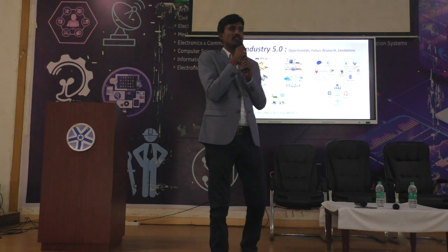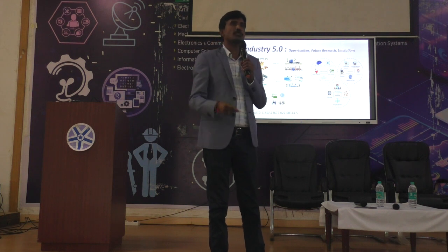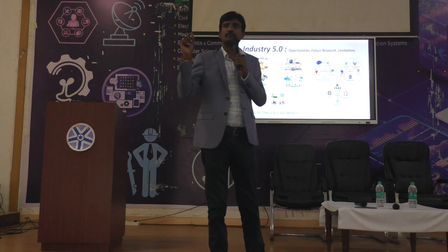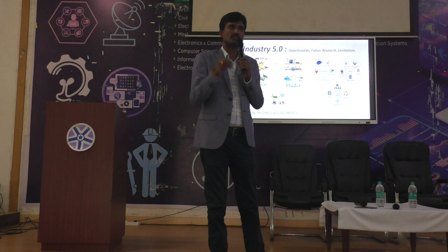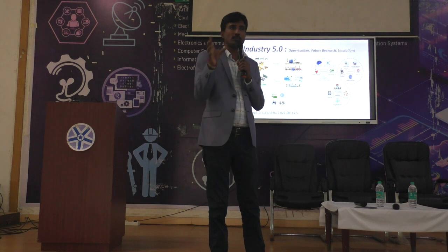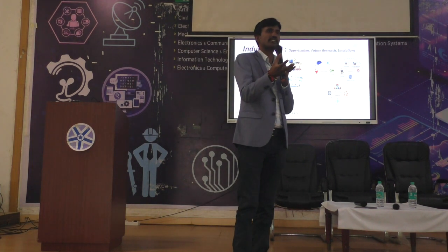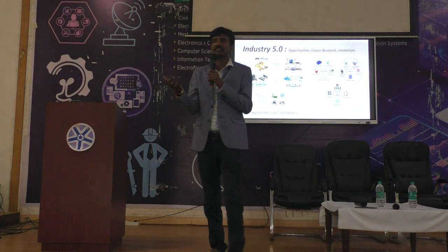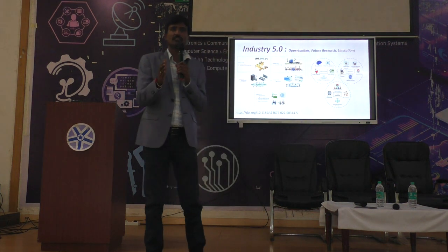So what people are developing, while developing the cutting tool materials, at the surface level, they are embedding some graphite or solid lubricants in it. Because of the presence of the solid lubricants, lubrication is happening without the help of liquid lubricants. So the problem of handling liquid lubricant has been taken care of. So it is a sort of development.